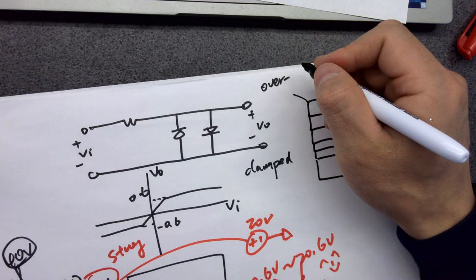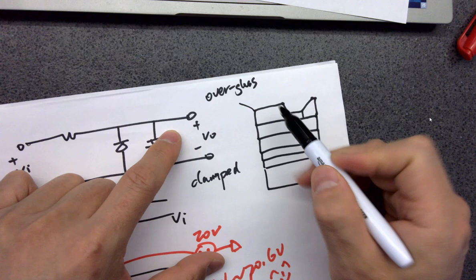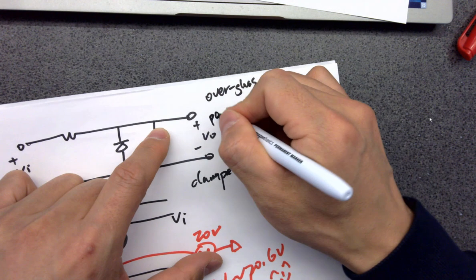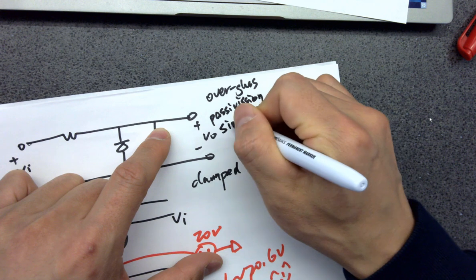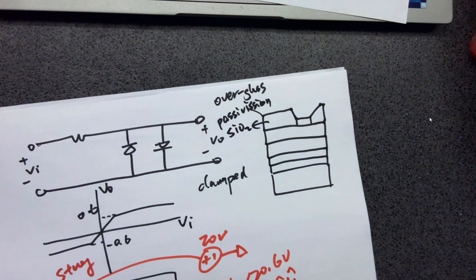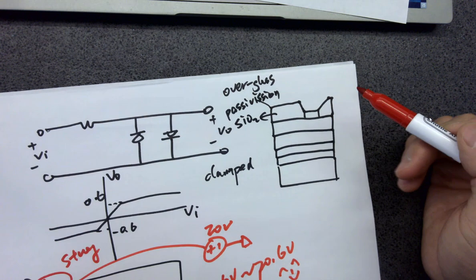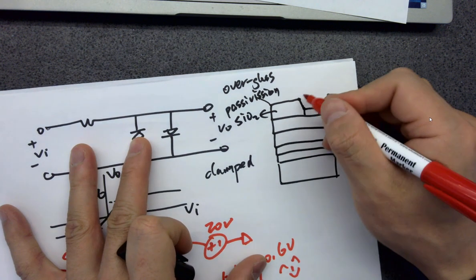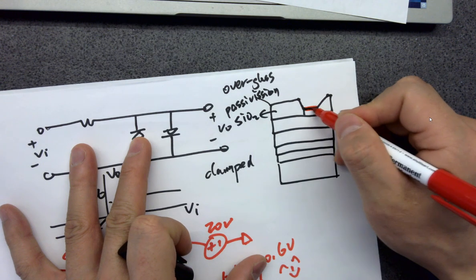Over glass? Forgot. That's the opening. So this is called passivation. It's a passivation layer. It's also silicon dioxide. But you can have an opening on the top from one of the masks. It's a device from the library, and you can open it up on the silicon dioxide. So this one is exposed to air. That's metal 3.